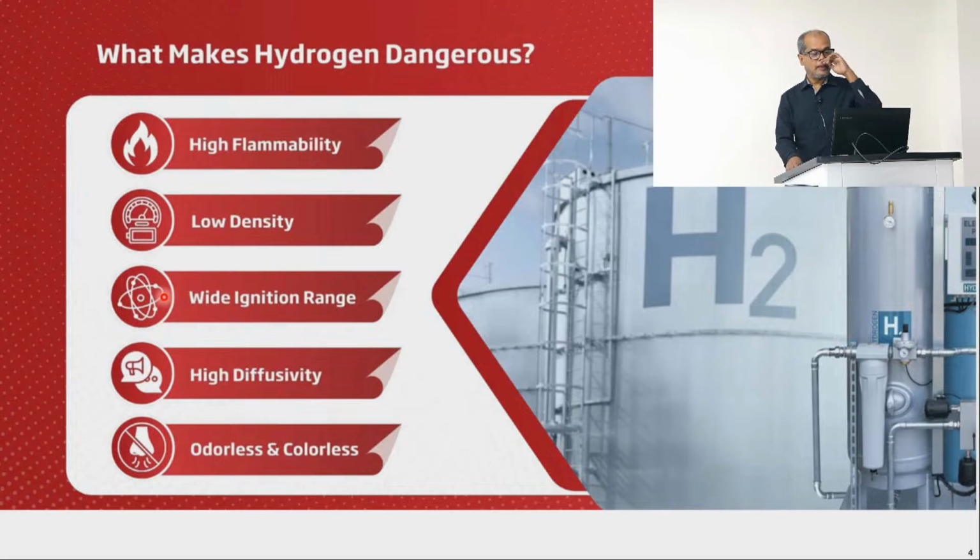And what actually makes hydrogen so dangerous? A few of them I already mentioned. These are the things: high flammability, low density, wide ignition range, high diffusivity, odorless and colorless, that actually make hydrogen more dangerous than other gases.